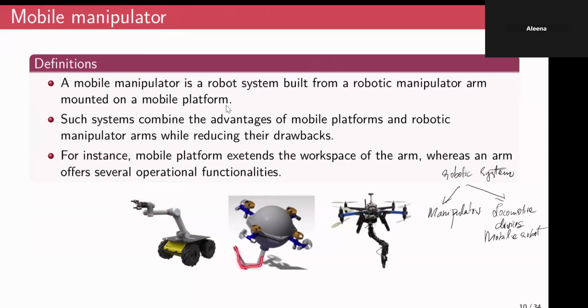So this is another example where a manipulator is mounted on an underwater robot. The way an underwater robot moves is using thrusters mounted in different directions. Here, you may have 8 thrusters, two of them facing vertically upward, and four of them facing in a direction orthogonal to this vertical direction.